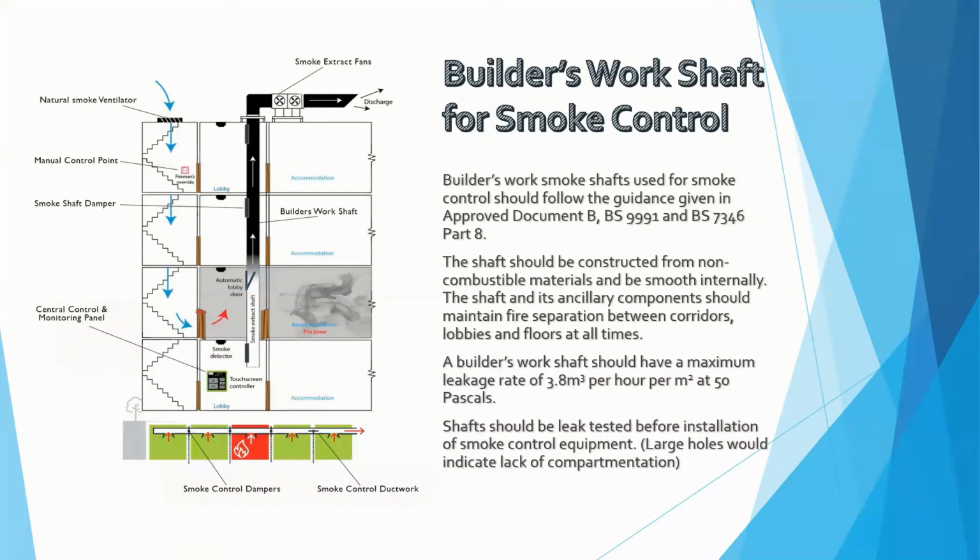This schematic drawing is a typical stairwell arrangement, together with its purpose, and its products associated with controlling and forcing smoke into the building's smoke shaft away from the stairs and the lobbies. Guidance is given in Approved Document B, BS 9991 and in BS 7346 Part 4.